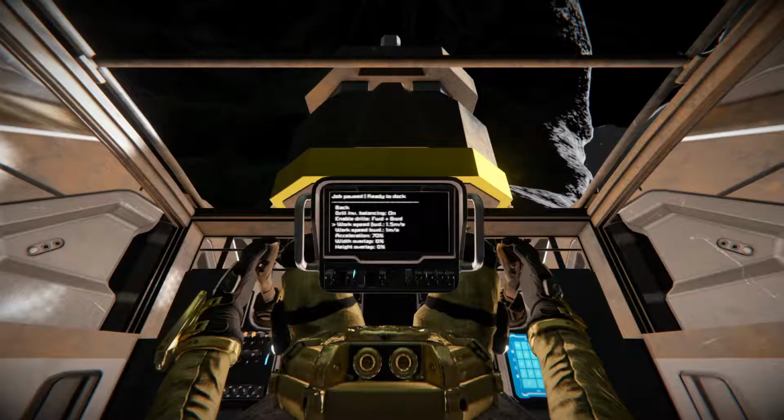It also means that, say it's halfway through a hole and it's filled up, so it's returned home, dropped off that ore, and it's on its way back, it's going to fly at 1.5 meters forward into that drill hole until it connects with the stone. Keep in mind, it won't stop just short, it's going to keep going at the speed you set. So if you set this too high, it potentially can impact the rock wall at the bottom with enough force to break your drills. So try and keep that one on a little bit of the slow side, is my personal opinion.